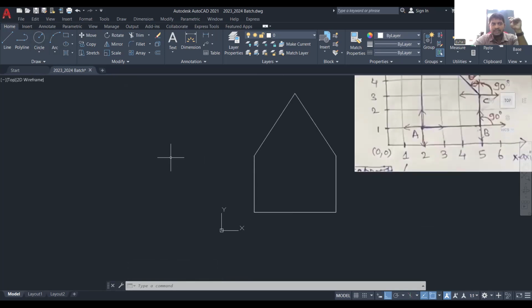To draw the circle, you can use C enter. C enter is the circle command. Otherwise, you can click this symbol. That also works; you can open it two ways. Say I do C enter. Then I specify a circle center point.